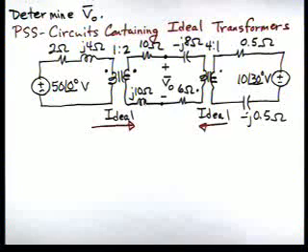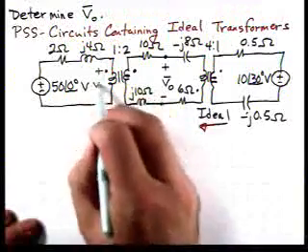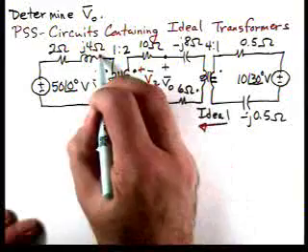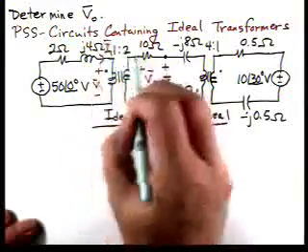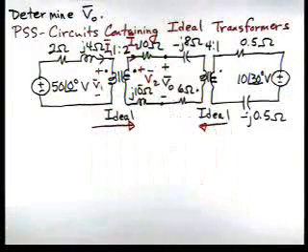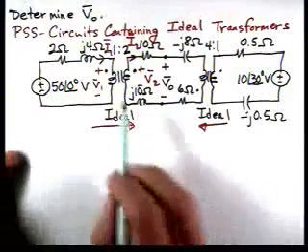So if we look at our strategy, it says look at the relationship between the dots and the voltages. Well, we really haven't got any voltage here, but let's go in and label this one, for instance, V1, V2, and let's label this current I1, this current I2. The voltages are both referenced with respect to the dots.